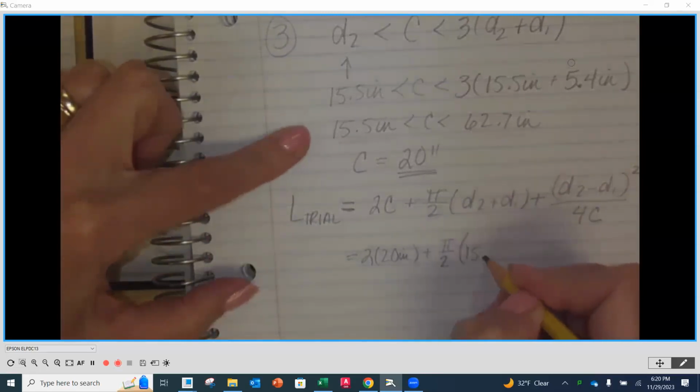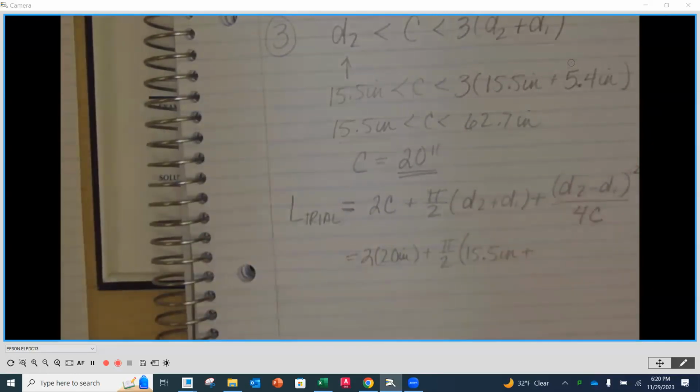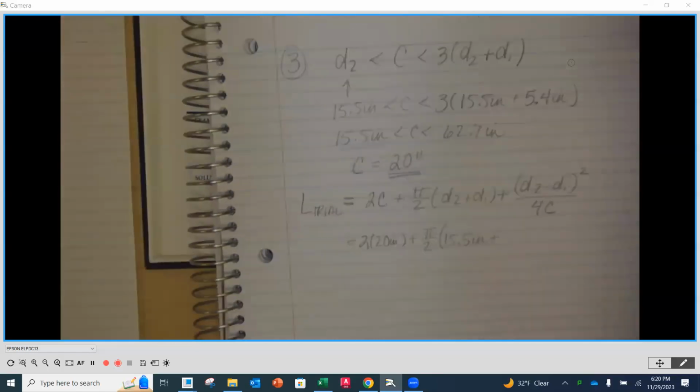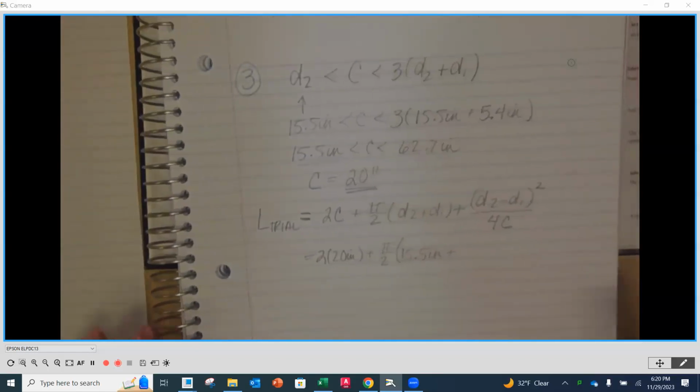D2 is 15.5. Another point, when we pick elements for a drive, most often you want it to be as compact as possible. I'm not saying that their design isn't good, but usually you go towards a more compact design rather than a big thing. For this grinder, it's stand up, so they want to put the motor as close to the ground as possible, keep the weight low. So maybe they're trying to get a height. You might be right.